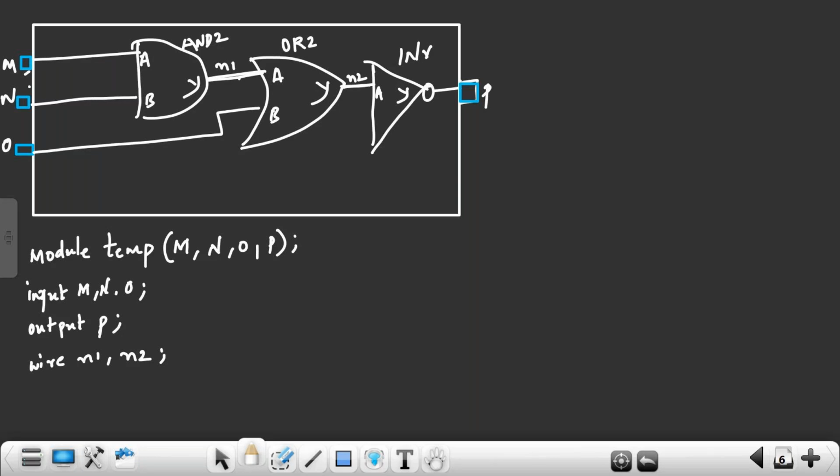Apart from this, in RTL you can see if statements, case statements or assign statements. But here you will see only gates and their connections. So what is the first gate I have? The AND gate, a two input AND gate. My synthesis tool will give one instance name, U1. This name is different for different cells, because in the synthesized netlist I can have n number of two input AND gates. The library name remains the same, but from one AND gate to another I need some difference in the name. For that reason my tool will give an instance name.